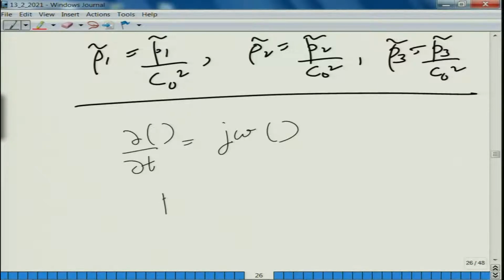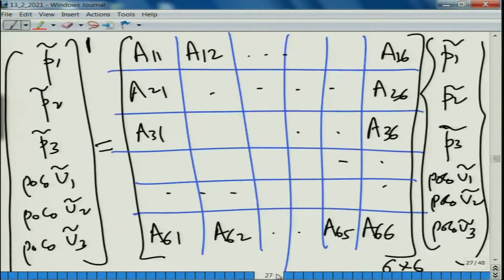Suppose it is p, so we get p tilde e to the power j omega t, and e to the power j omega t is cancelled on both sides of the equation. So, eventually we get this quantity, and this is often divided by the sound speed, so we replace this by k naught. That is a standard simplification process, you would have followed it by now.